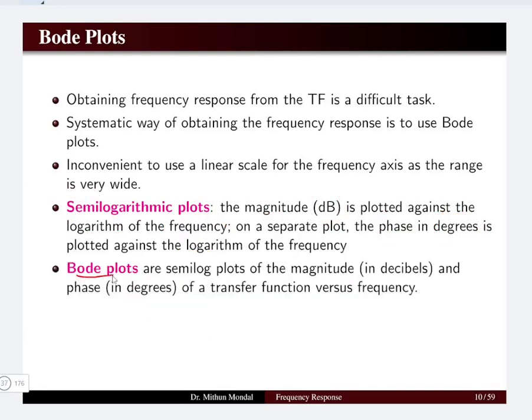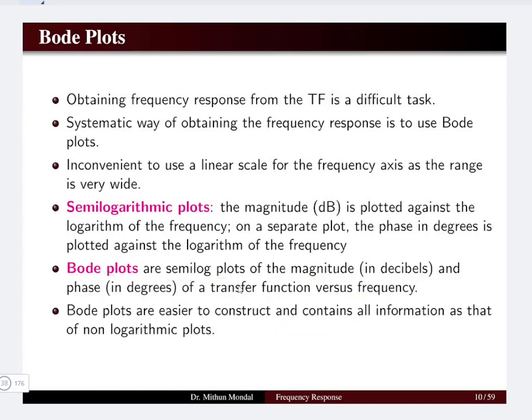Now Bode plots are basically semi-log plots where the magnitude is plotted in decibel scale and the phase is plotted in degrees, for the transfer function versus the frequency. The frequency is the logarithmic frequency, and the transfer function will have the magnitude in dB as well as the phase in degrees.